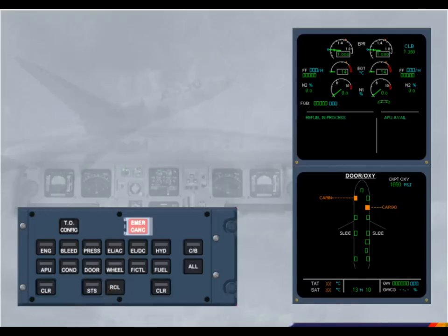During the pre-flight check, one of the things we do is check fluid levels. For example, the quantity levels for hydraulic fluid and engine oil. The required system pages are manually called by pressing the associated key on the ECAM control panel.